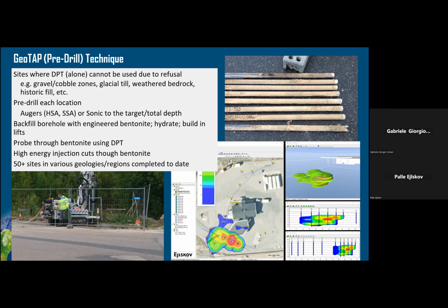And the example we have on this slide is from a site in Finland, where we managed, with not a few challenges, to perform a remedial design event by doing direct push and going down with 2 different diameters of piping to collect the samples that we needed. At this site, we took 425 soil samples. You could see the highly homogeneous sands that we had to go through, and direct push is not that easy because you're trying to displace something that is highly compacted.